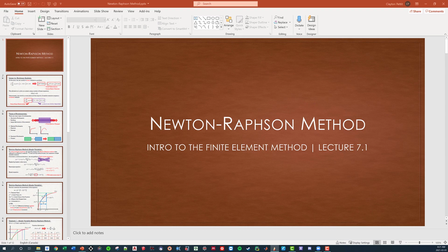And what's nice about a linear analysis is we can do this independently. This is why linear analysis is so easy: we can do that stiffness matrix all by itself. Now, if we were to look on the other side, if I were to say, well, I also need my nodal forces. Can you guys figure out what our nodal forces are? What do you guys think? Can you guys figure out our nodal force vector? I hear another yeah. Exactly.